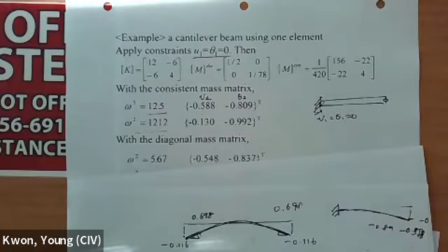Because the equation looks just like the one that you used to calculate deflection. The deflection equation of that cantilever structure with the tip load is exactly a cubic polynomial, which is the basis of the shape function. So in other words, your trial function can pick up the exact solution from there. That's why you got the exact solution.